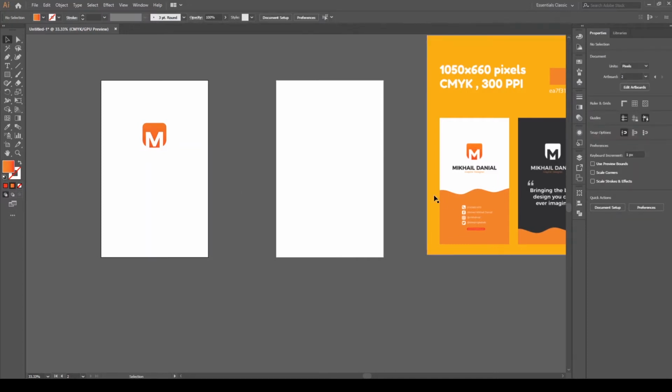So next part, we're going to use brush to make this pattern. This one needs a lot of practice, but then it's easier to do it this way rather than using shapes. If you are not familiar with pen tool, another way is that we can use brush. How to use it? You can just press B for the shortcut, or just select this icon here, paintbrush tool, and then okay, change the color to orange first. Press I, click this color, and then press B for the brush tool.